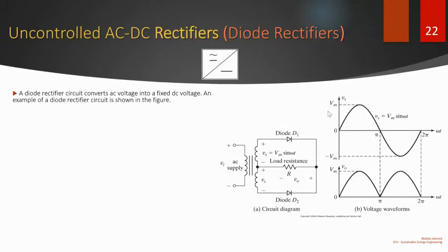Mikhail, yes. For the DC-DC converter, would that need an inductor to boost the voltage? So we'll get to that. DC-DC converters are similar to the voltage multiplier circuit that we had. Remember the voltage multiplier circuit that could multiply the voltage by 2, 3, etc. So for the boost one, it's similar to that.